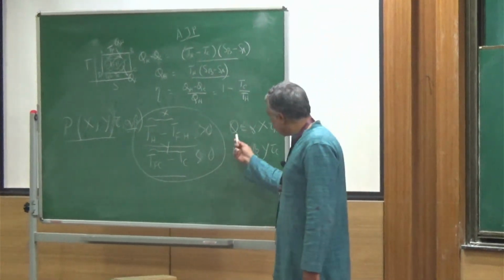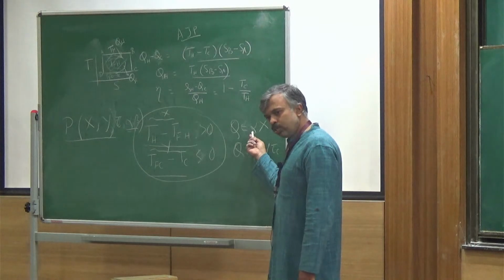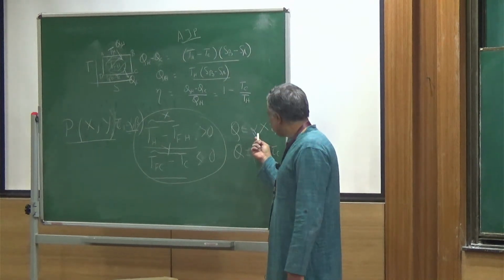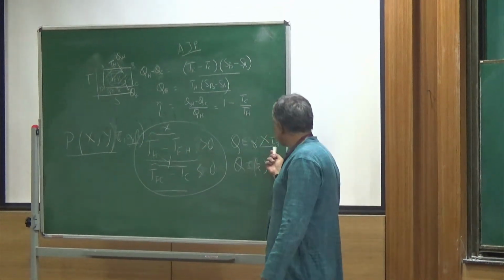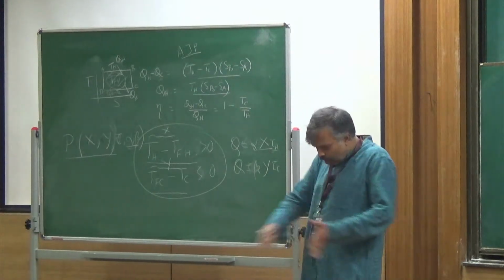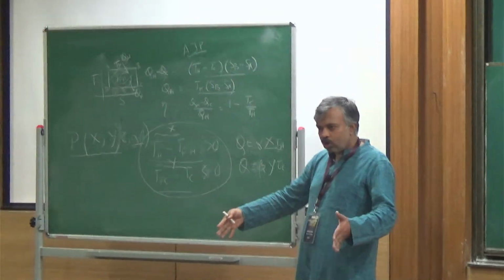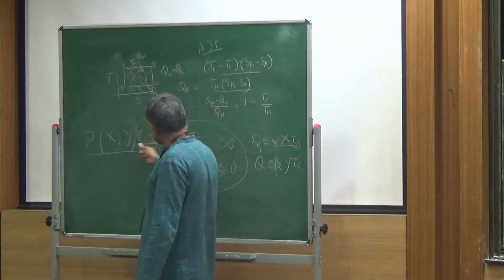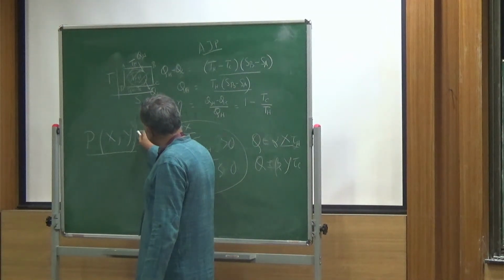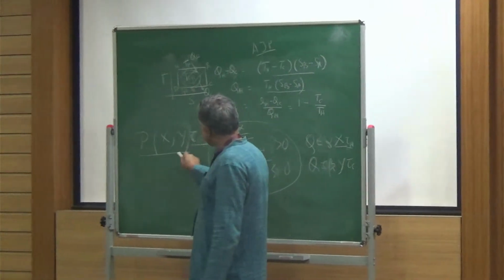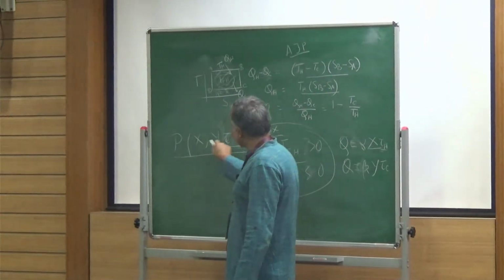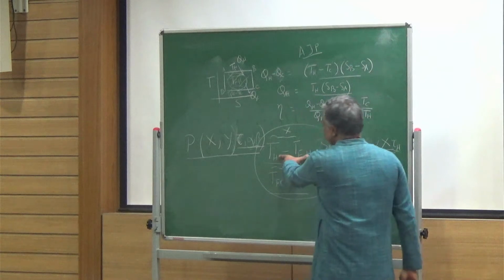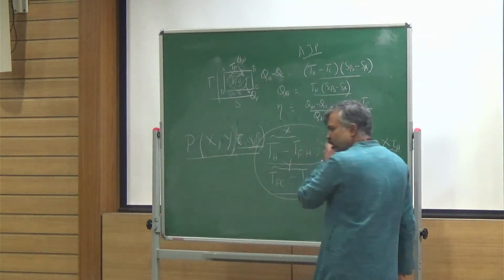So the heat that goes in is proportional to the heat conductivity constant, then this x, the difference, and then the time scale tau of the hot isothermal. So these parameters go in here. This is the total cycle time tau, alpha, beta, and this function of x and y, which is the temperature difference between the bath and the fluid.